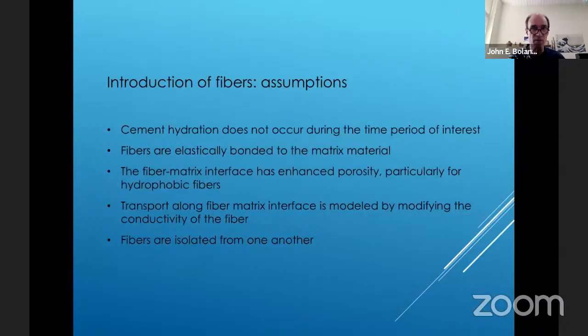So now we add the fibers, and there are some assumptions we have to make. That cement hydration is not occurring over the time period of interest. The fibers are elastically bonded. That's a big assumption. Think of the material at that early age. We're assuming it to be elastically bonded to the matrix material.